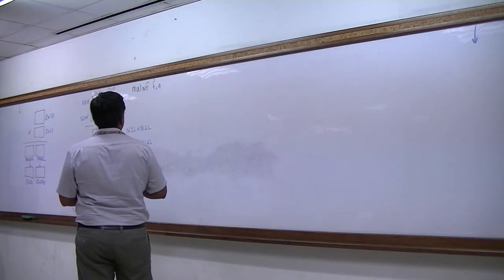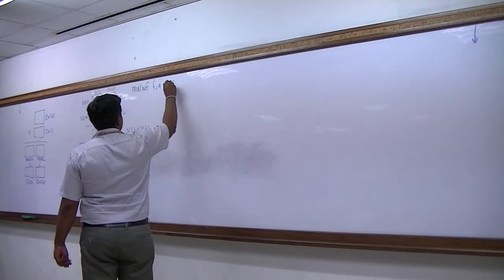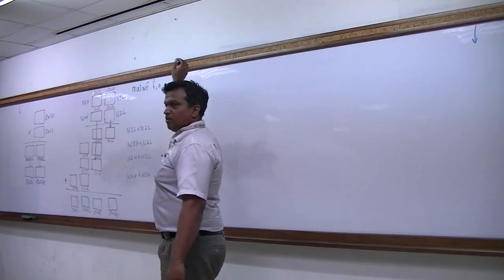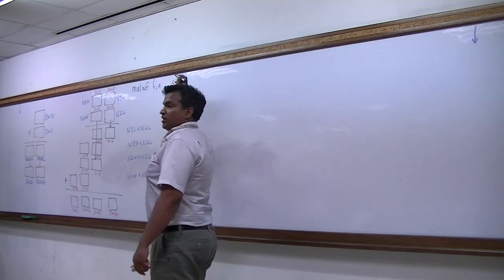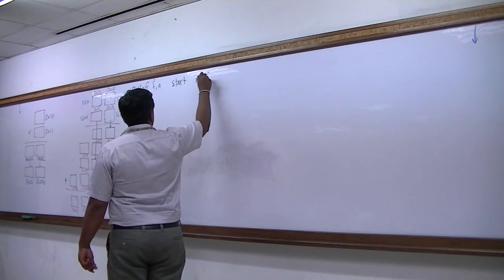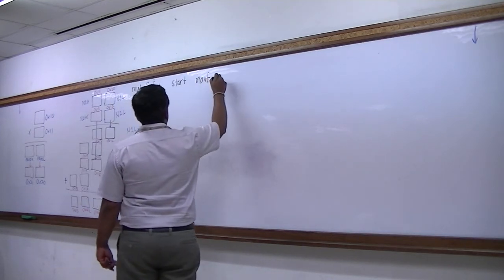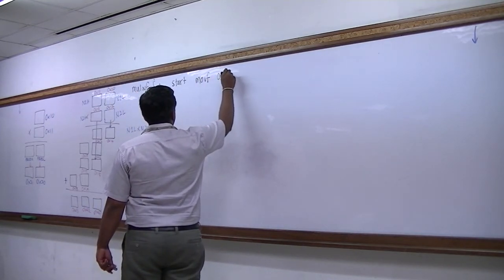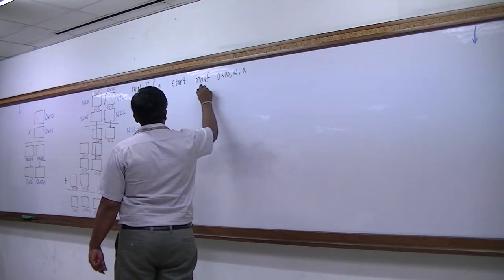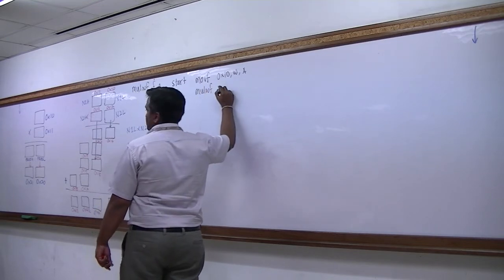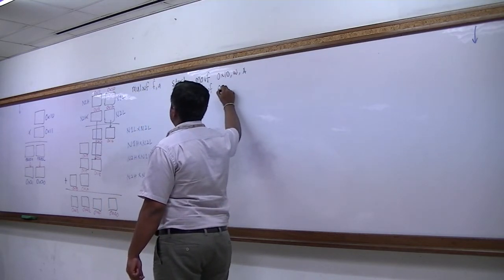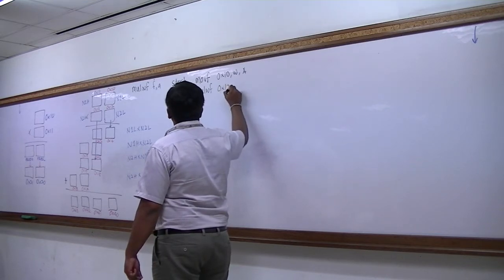So assume that on top I have declared all my program start template and everything. The first thing is you're going to move the content of x10 to the working register, and then you're going to multiply with which file register? 12.